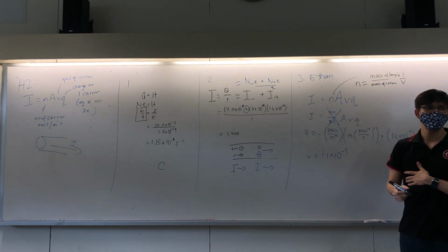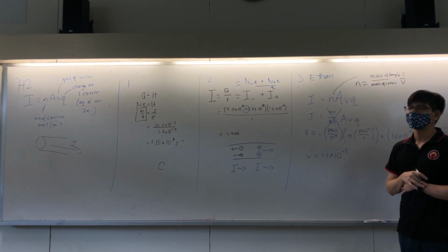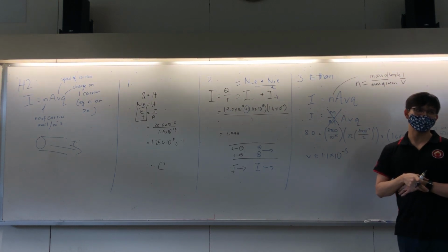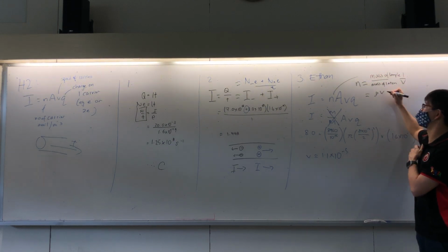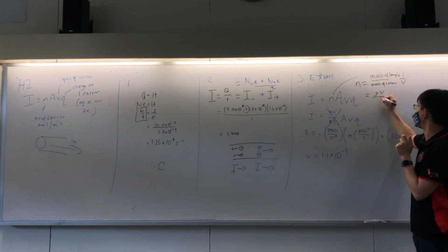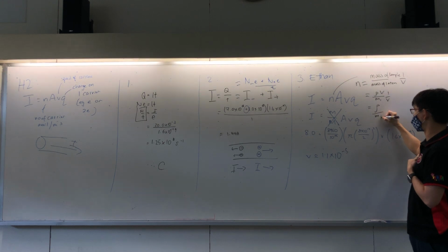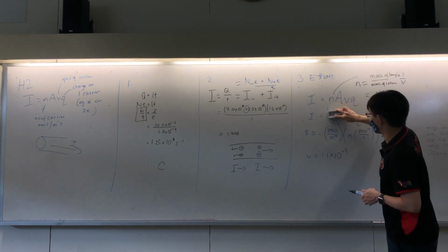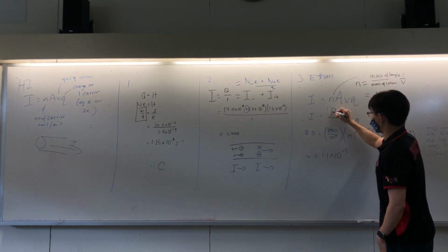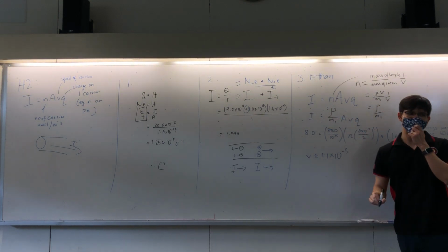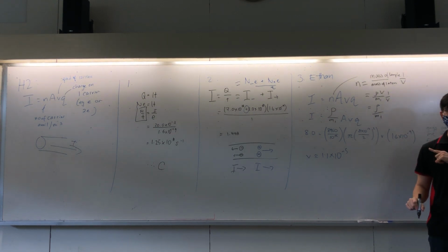So it's density over one atom's mass. To show that, the mass of the sample is the density of the sample times the volume of the sample. Then this is the mass of one atom. Then 1 over V. That's why this is density over M1. So what Ethan should have right here is not mass of the sample over M1, but rather density of the sample over the mass of one atom. Then this will give you the number of charge carriers per unit volume.